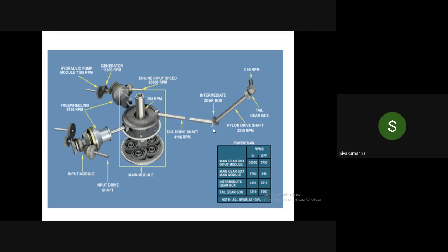Everything, and the only thing he could not have was the engine, because he wanted to build it but the cost was going elsewhere. He showed that when you move the collective and cyclic pitch lever, the transmission goes through the links to the swash plate mechanism and to the blades. So practically he had a structure.